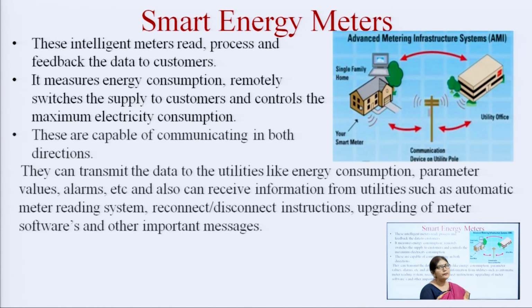So, this is the basic structure of a smart meter. Here the smart meter is placed at any home, and this is the utility office. The utility office can monitor this smart meter through any communication mode, like GSM, high frequency modulation technique or any other technique. From the utility office it can measure the instantaneous value of the energy consumed, and the highest energy consumed by that house.